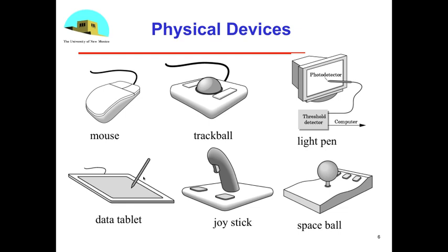Joysticks are interesting devices. We don't use them as much as we did, except in special applications like flight simulators. But the important thing about those that I want to keep bringing up is that you build a joystick so it has some resistance in it. There are springs and masses and dampers in there, so that the more you push against it, the harder it is to change the position that it's measuring.